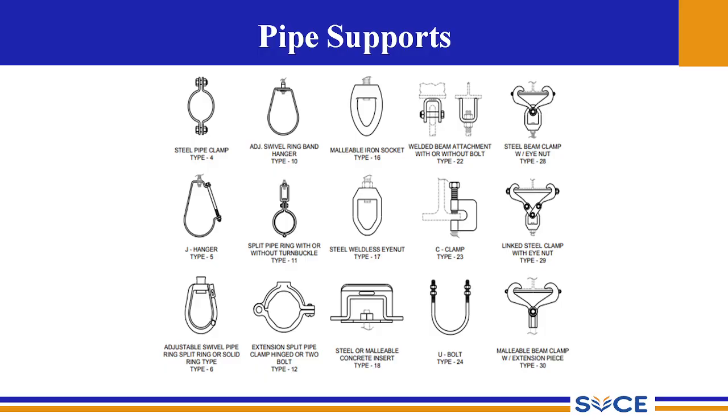Then we can install this turnbuckle adjustment after or even before the pipe is properly placed. So there can be adjustments so that the pipe can be oriented properly, and the stress accumulated can be mitigated.